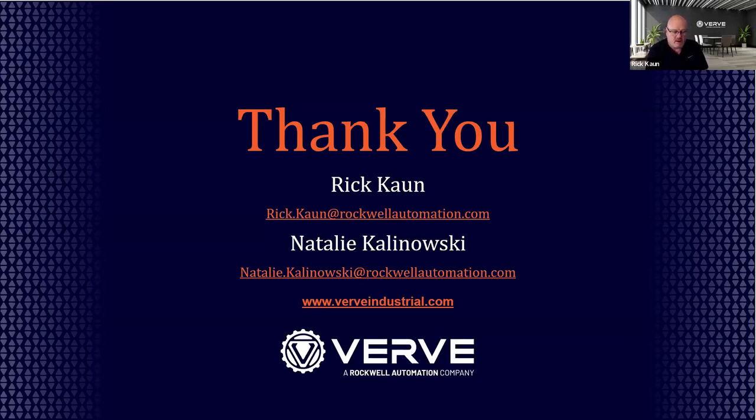So for those of you who are aware, Rockwell has a database or an inventory type of tool set called the Factory Talk Asset Center. There are two dimensions in which it is significantly different from Verve. One is that Asset Center was primarily built for Rockwell kit. They are expanding to support friendlies like Schneider equipment, et cetera. But it was originally built for managing all of those PLCs and relays and VFDs, et cetera. So there is a heavy emphasis on maintenance, on ladder logic check-in. There is some vulnerability mapping. There are ties to other data sources from the Asset Center that include playbooks for updating firmware.